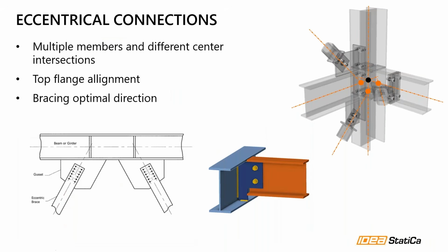And we can move on to the eccentric connections, because on every structure there exist some eccentricities. They basically allow practical detailing, accommodate geometry offsets, enable bracing layouts, and provide space for cladding or services, for example, even though they introduce moments and are often unavoidable to meet architectural and functional requirements.